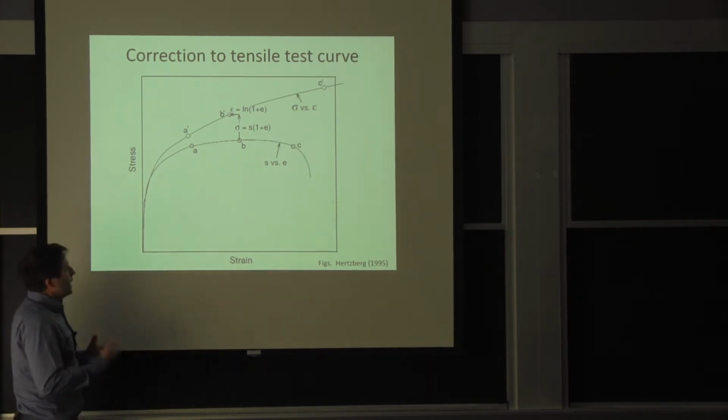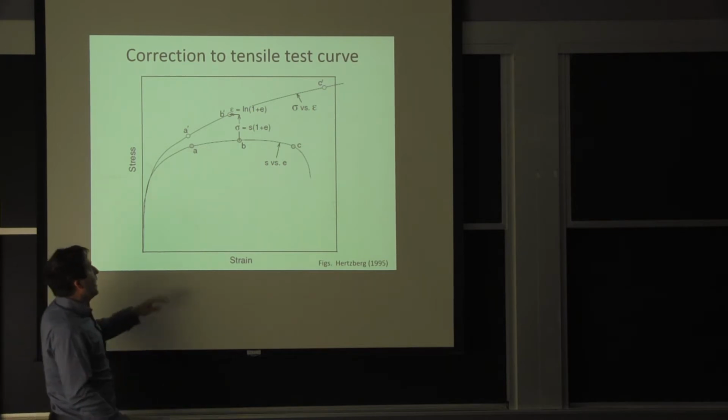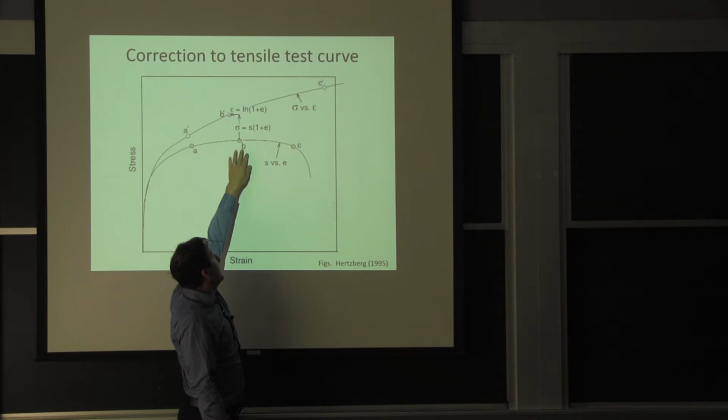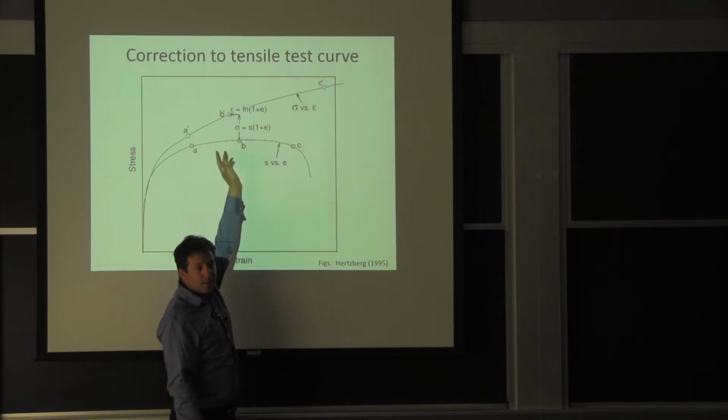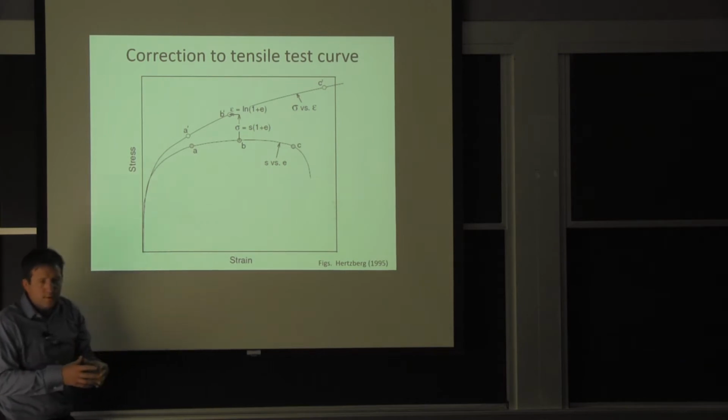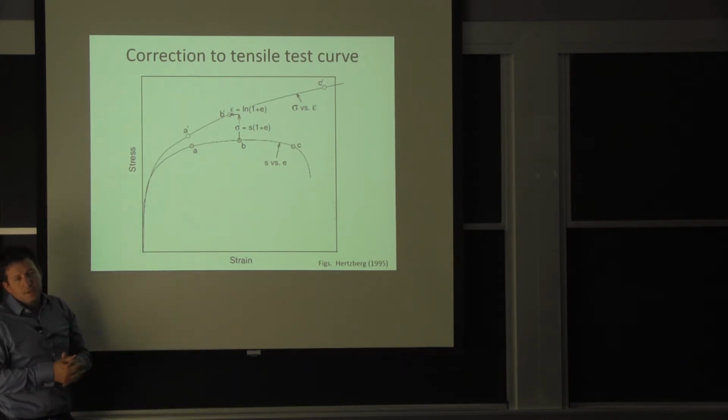So if I only have the stress strain curve, I know that for my computer program, I need to tell them that there's actually hardening, because the computer program knows everything about the reduction in cross-section. It can essentially work with the actual stress-strain behavior of the material as opposed to the engineering representation that we use.